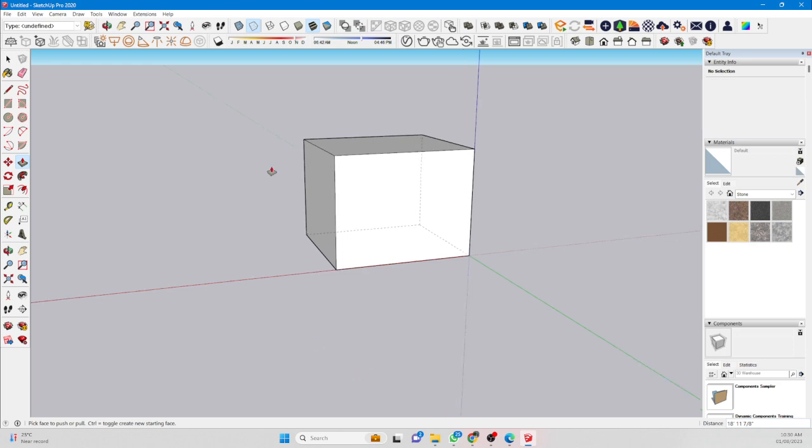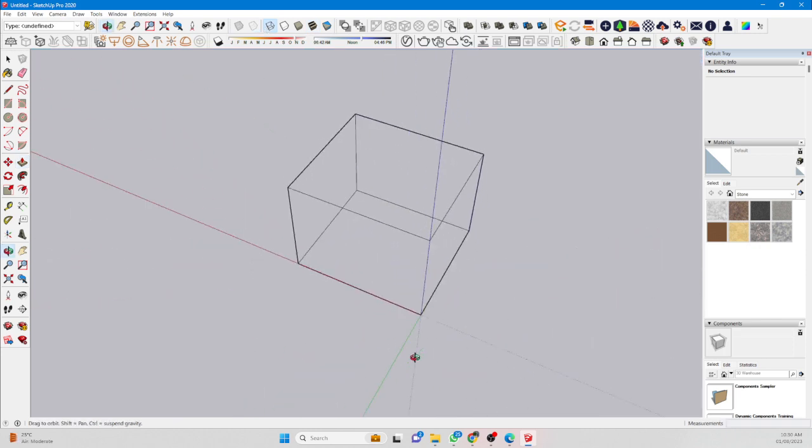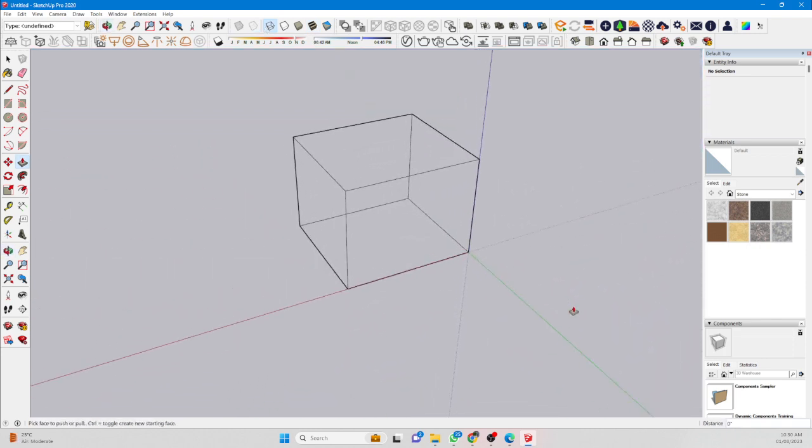After this, the edge view, so you can see the hidden edges, only the edges, you can't see the faces. After that this is the wireframe. You can't see the faces in the wireframe, you can see only the edges. Another one is hidden line, same as the wireframe, only you can see the hidden lines. Then this is solid. Shaded, it's called shaded. And this is shaded with textures, if we have any texture for this, see.